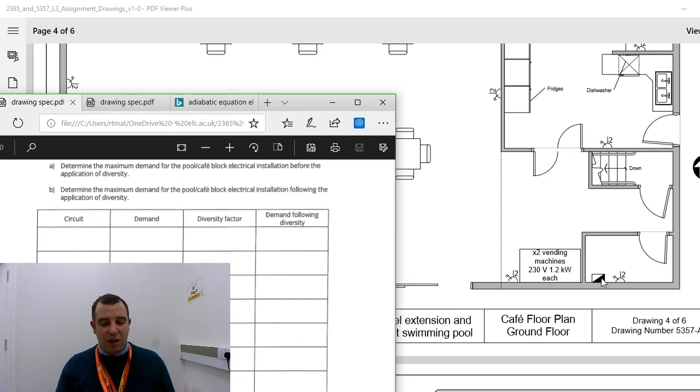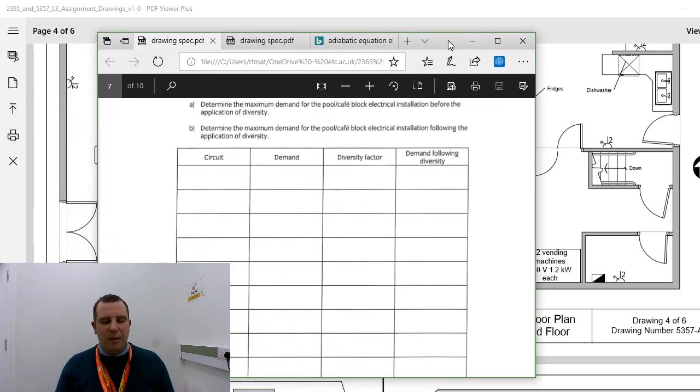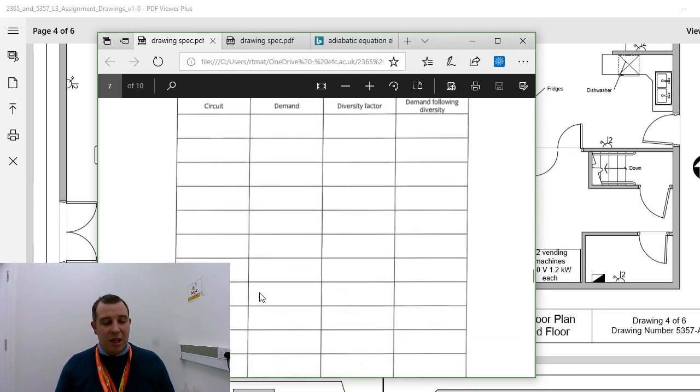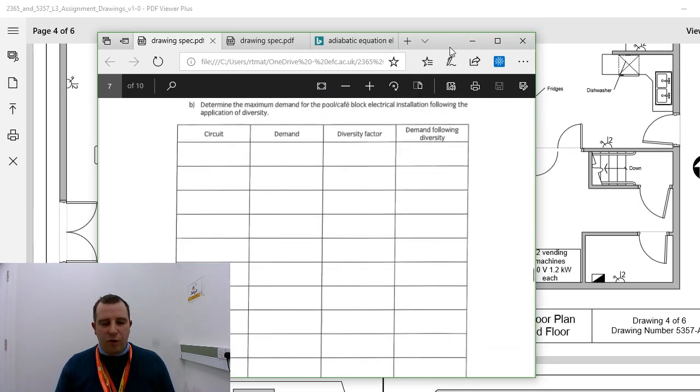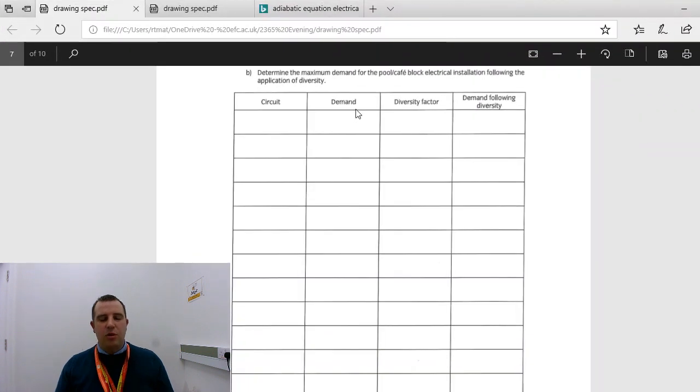Yeah, so if you've done a circuit chart here and you can identify it to here, then it makes a lot more sense. But again, think about that, and talk to somebody if you're unsure what that exactly means. The main thing is you've got to get all your circuits listed down, and you need extra tables on this. Once you've got all the circuits listed down, what you need to do is work out the demand, which sometimes is breaker size, sometimes it's actual demand. But if we don't know, then we've got to decide diversity factor. And this question's more about diversity factor than anything else.